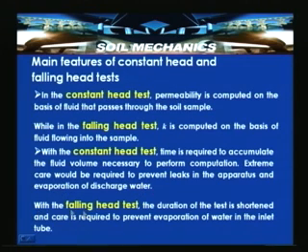In the case of the falling head test, the duration of the test is shortened and care is required to prevent evaporation of water in the inlet tube. Evaporation of the water in the inlet tube can influence the results, so that has to be taken care of so that the evaporation is minimal.